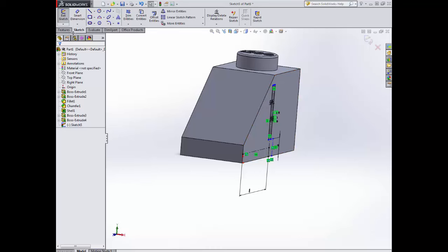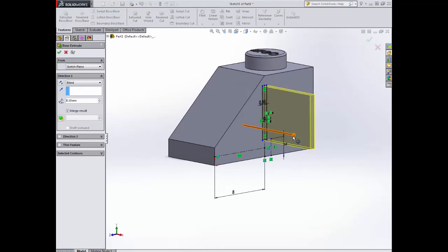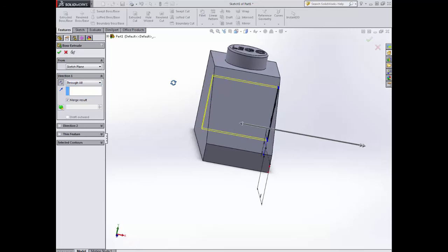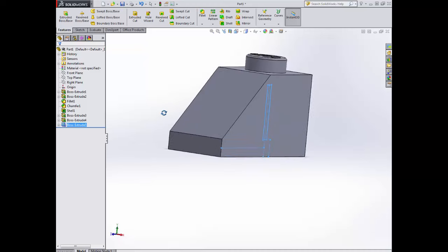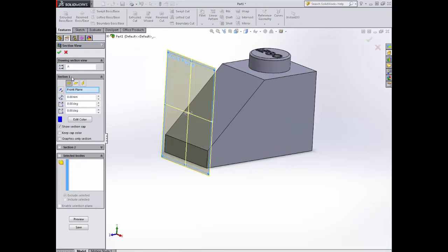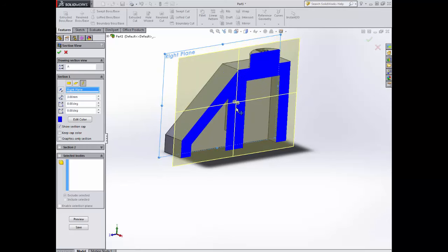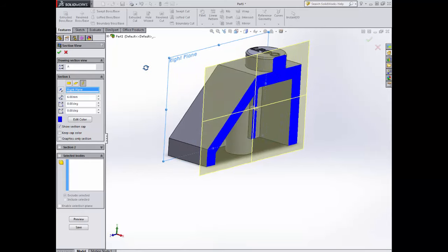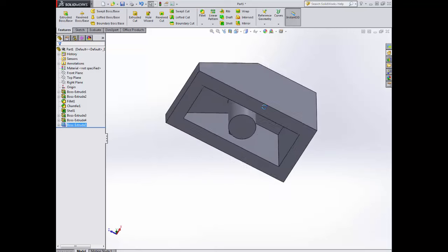As I said, I'm now going to extrude this across the shape. So at the moment preview's sticking outside. I can drag it in the right direction, and then what I can do is I've got an option here, and I can say through all. You could give it the right distance, you could go to next face, so there's lots of options for us to do here. So now we'll go back to our section view, and what we need to do is make sure that that top edge meets perfectly. And as you can see, as I move my way through here, you can see that it actually touches the top very nicely. So green tick that, or red cross it, because I don't want the section view anymore, and that's my shape.